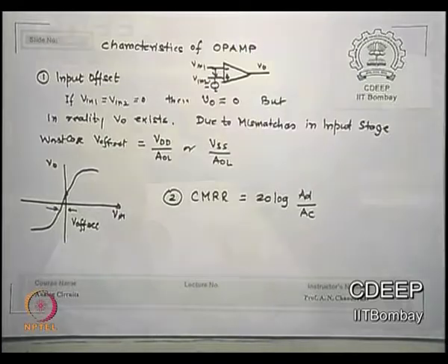There are two kinds of offset. Which can be the two kinds? One of them can be random offset, okay. The other can be systematic offset. It is much easier to cancel systematic offset, because every time it moves there, I will actually put minus there so it comes to 0, but sometimes it goes there and sometimes it goes there. How do I do it? So random offset, which is essentially noise related, cannot be cancelled, but systematic offsets can always be cancelled. Is that point clear?